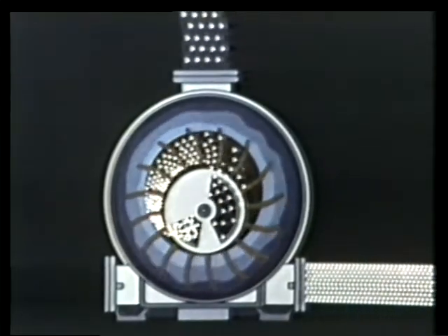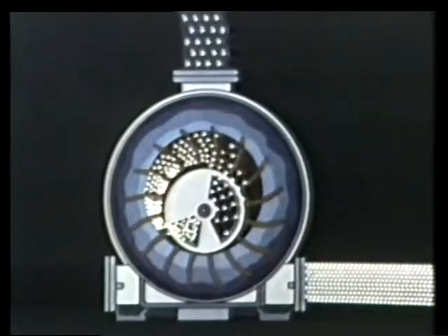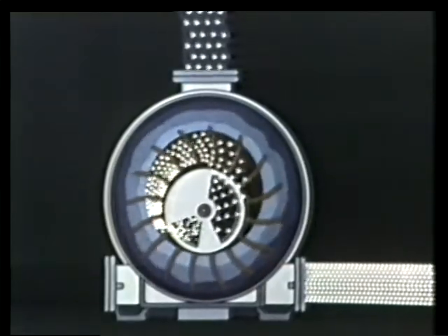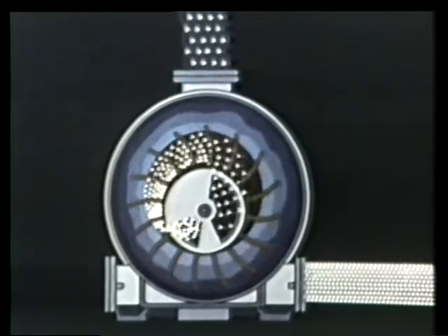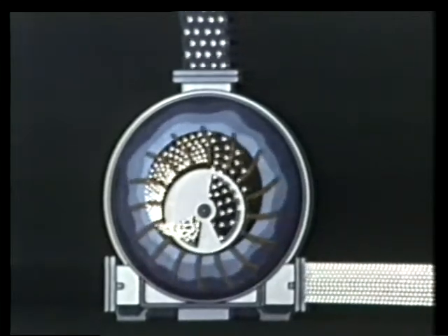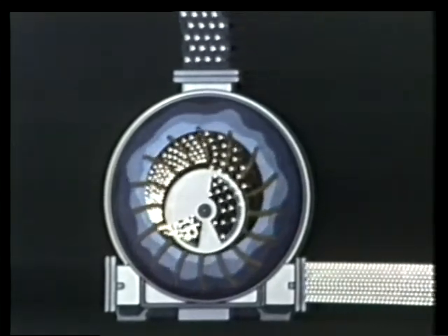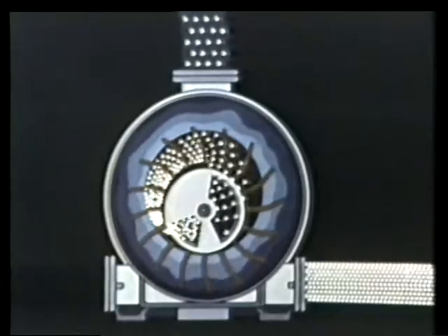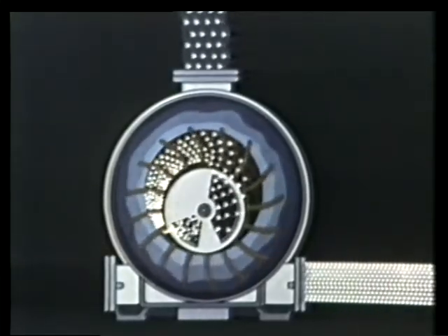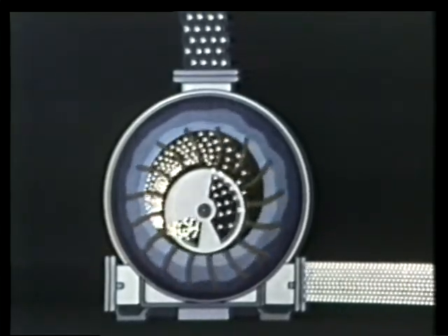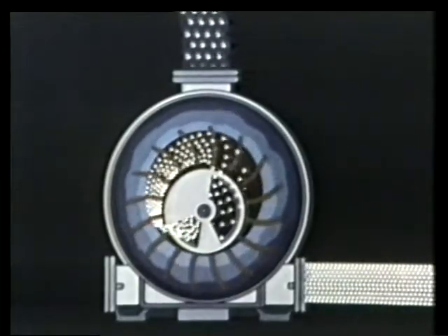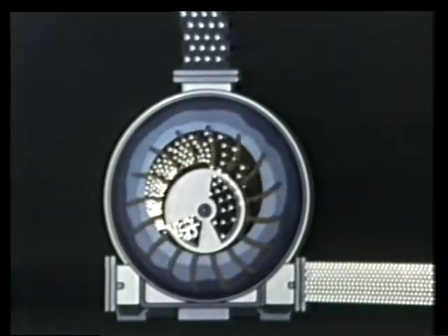In some ways, this is the simplest of all compressors. The rotor is the only moving part. Because of the off-center arrangement of the rotor, water acts as a piston to compress the trapped air. The constant flow of water also cools the compressor, so no additional cooling's needed. However, moisture separators are required to remove the water that's picked up by the compressed air.